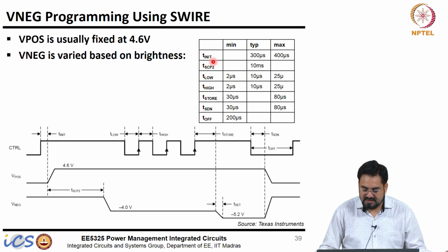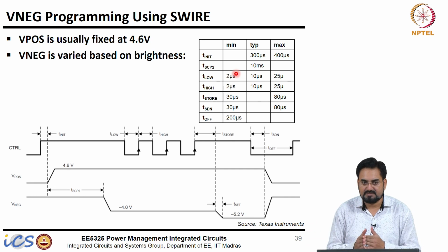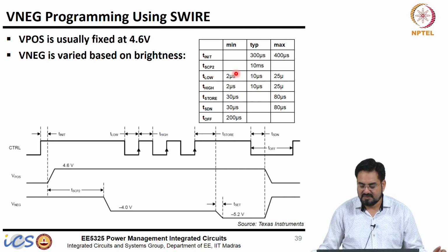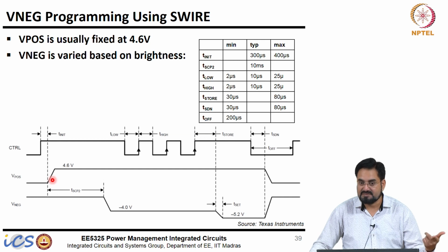And then after that you have the short circuit protection. The 10 millisecond wait is given before you turn on the negative supply in order to make sure that short circuit is not there. So, let us say somebody has shorted, so your supplies will not ramp up. Basically it is more like a timeout signal you can say. When the 10 millisecond has passed and still your supply is not ramping up, then, we know that we need to turn on positive supply first and negative later. We do not want any instance where negative is turned on and positive is not there.